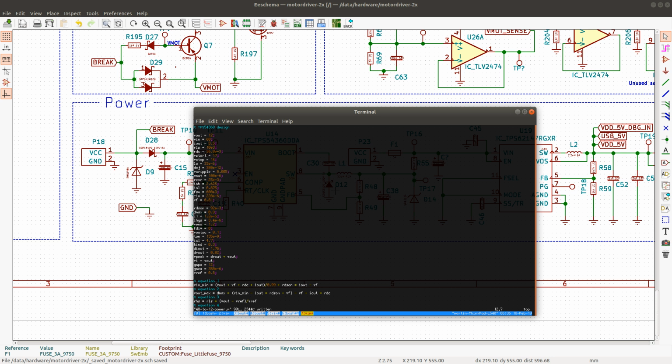This is the output voltage ripple in percent, or rather just as a number, sort of as a fraction of the output voltage. So I set this to 0.5%, just like the value that they used in their application. This is my output capacitor. I set it to 100 microfarads because I want to see what will happen if I reuse as many components as possible. And this is the ESR of this output capacitor.